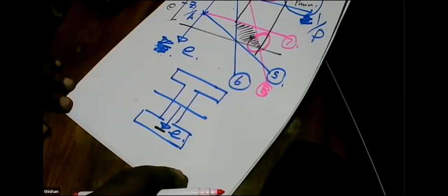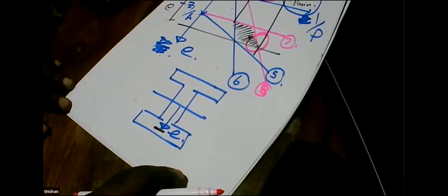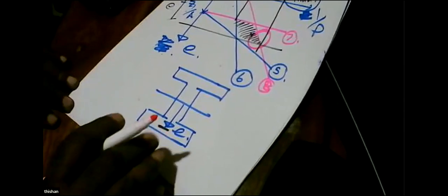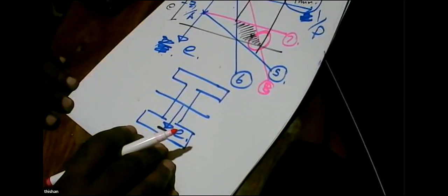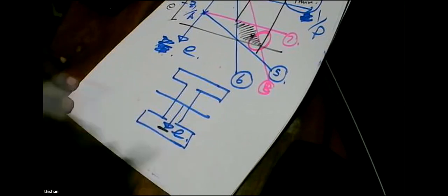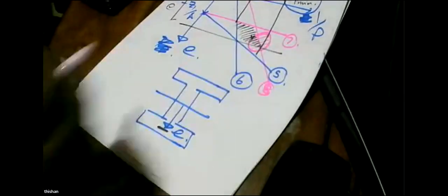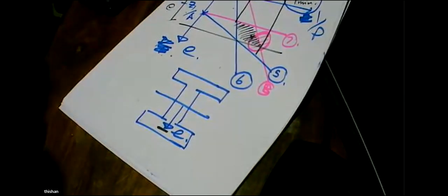The cost of pre-stressing steel can be about 2 times the cost of reinforcing steel. Right, so pre-stressing steel is about 2 times the cost of reinforcing steel. So even in reinforced concrete structures, we try our best to reduce the amount of steel. Now in pre-stressed concrete, we should be trying even harder. Because of that, we always try to concentrate in this particular region that is giving the minimum pre-stressing force. Right.